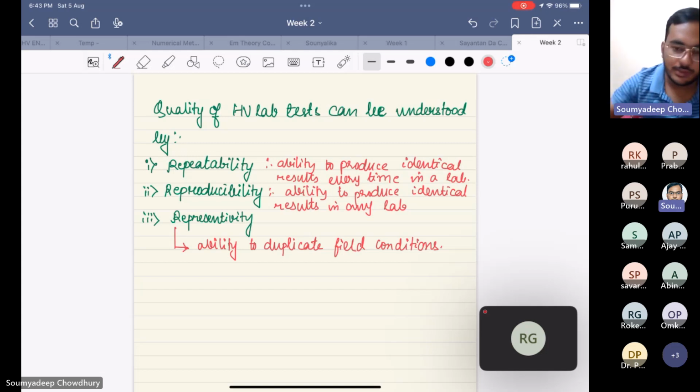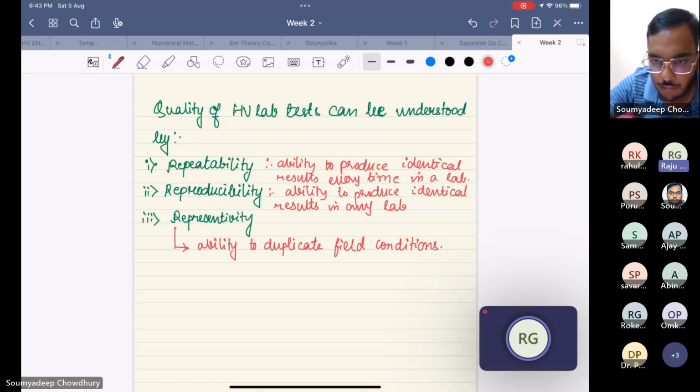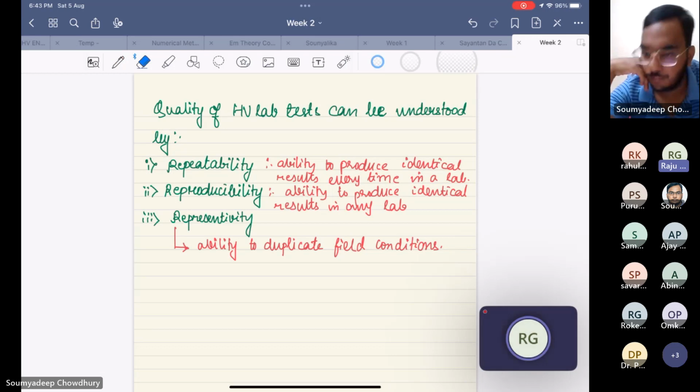One doubt. See, repeatability: you are saying that suppose you test an insulator in the evening at 10% more than the standard normal voltage. When you test the same insulator on the second day, because you applied an extra 10% voltage, the property of the insulator itself will be slightly less, because you tested it at a higher voltage. Therefore the conditions will not be the same. It is deteriorating it, and the next day when you test it, certainly it may fail, it may not give the same result.